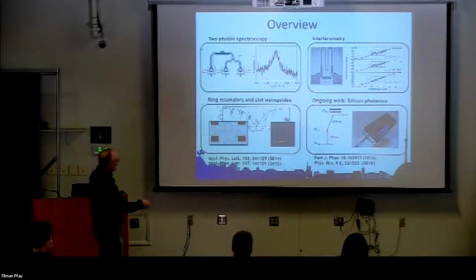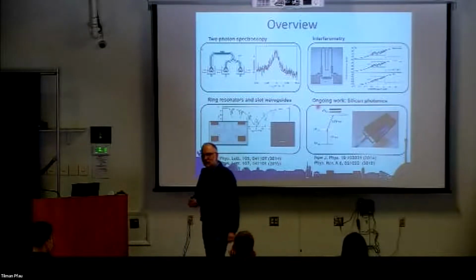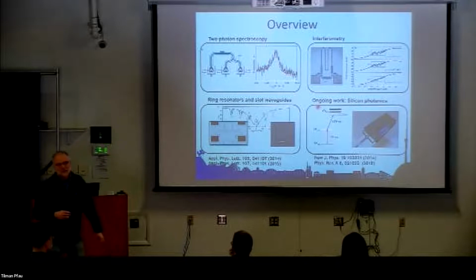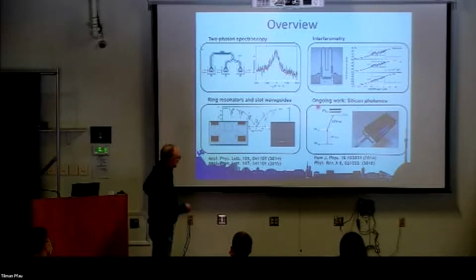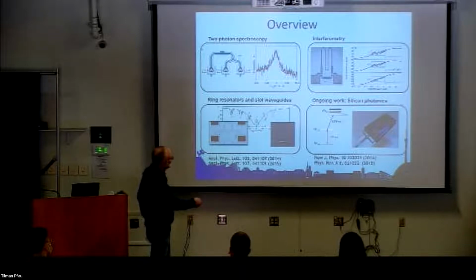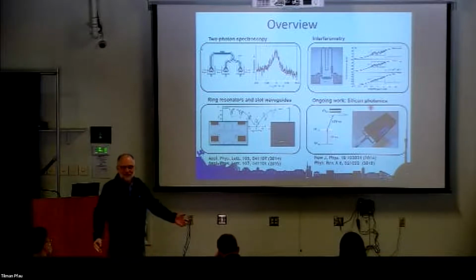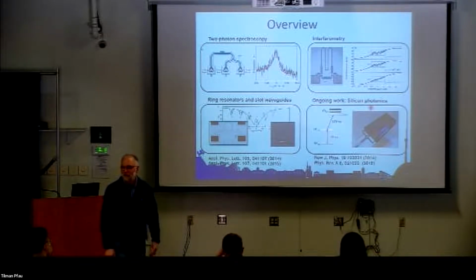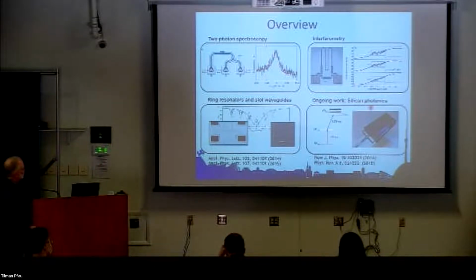What is also interesting is that the rubidium atom provides you with a wavelength from that excited P state that is 1.5 micrometers. That's interesting because that is a wavelength that is transparent in silicon. So silicon photonics can be used in connection with vapor cells as well. And I will show you some more examples of this. Yes. So a cell with silicon photonics looks like this. By eye, it looks black, yes. But of course, at 1.5 micrometers, it's highly transparent. It has very good optical qualities. Okay.